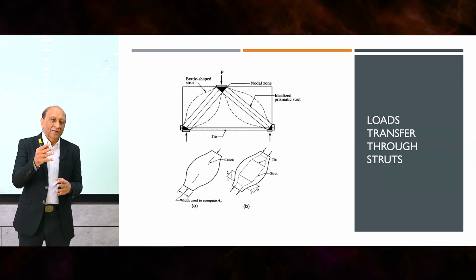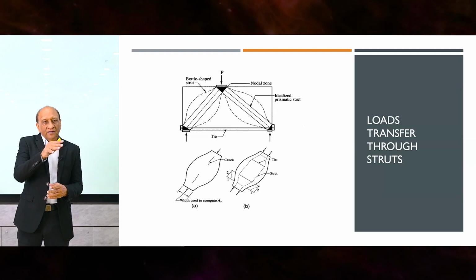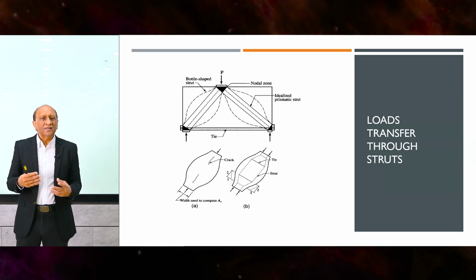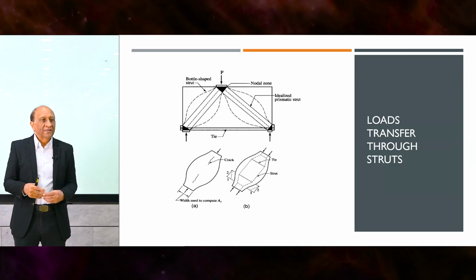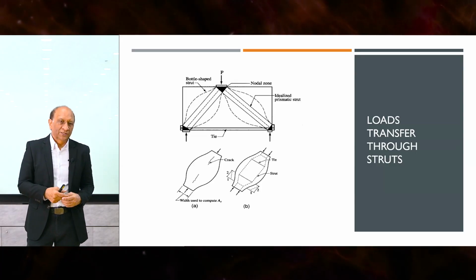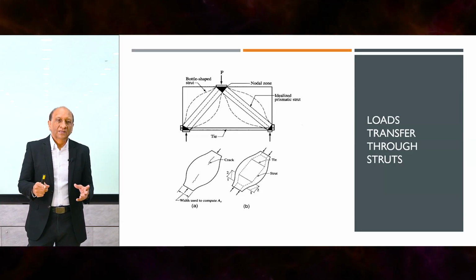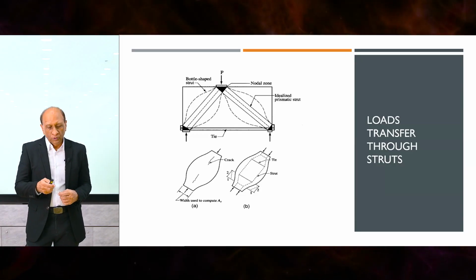So in the middle, you will expect a crack in the strut, and to prevent that, secondary reinforcement may be needed, just like column confinement may be needed. So think of the strut as a column within a structure. Generally, this will be small, but for very heavy loads, this could be a problem, and this should be checked.